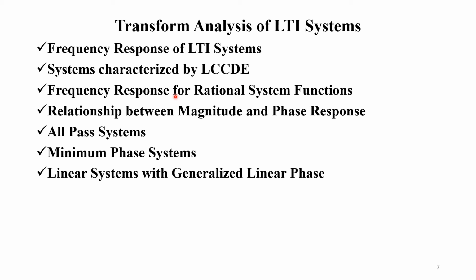Similarly, in case of all-pass systems, the magnitude response is independent of frequency, because the numerator and denominator factors are complex conjugates of each other and therefore have the same magnitude. So in short, we can say the frequency response magnitude is constant in case of all-pass systems, and it is the same for all the frequencies.